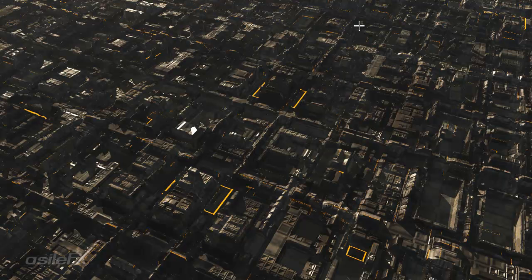That should start to look a little better, and we can start to adjust that as needed if we need to have more of a full coverage. So that did open it up a bit more. With this terrain, we do have a lot of curved areas, so we may have to go a little bit higher for that upper value, possibly even 0.95. We just don't want to go all the way up to 1. At least we shouldn't need to, although there is so much curvature it might end up being necessary. Really just depends on the slope level of the terrain.